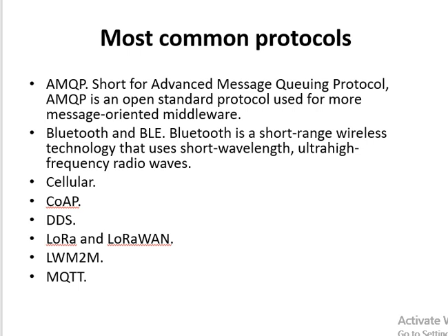So let us see about the DDS protocol in IoT. It is an IoT protocol developed by the Object Management Group for machine-to-machine communication. It uses a publish-subscribe methodology for exchanging data. It uses multicasting to bring high quality of service to the applications. In the DDS protocol, there are two layers named DCPS and DLRL. Now, LoRa protocol. LoRa is a physical layer protocol that uses spread spectrum modulation and supports long range communication at the cost of a narrow bandwidth. It uses a narrow band waveform with a central frequency to send data, which makes it robust to interference.